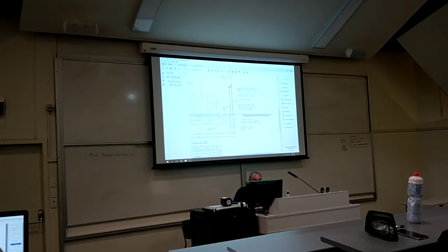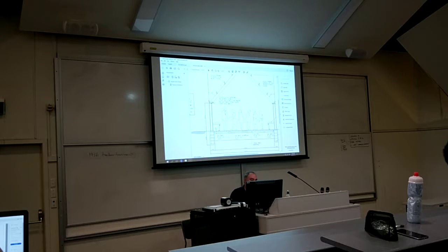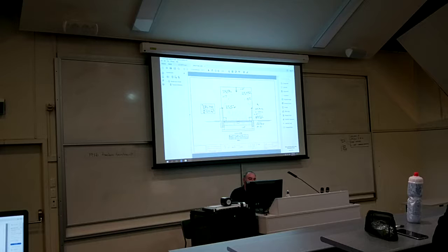I'm expecting these notes to be lined up and not hickledy-pickledy like my ones are. And I expect the leaders to be in the right place. In this case, this leader goes downhill from the top, which is incorrect. So you either move the note down and aim it upwards, or you do it from the bottom of the note. If you're unclear where an arrow should be, please ask me. This arrow is incorrect because it's pointing upwards from the bottom. This is incorrect because it doesn't have a leader line to it. So there's a lot of really bad dimensioning in arrows.